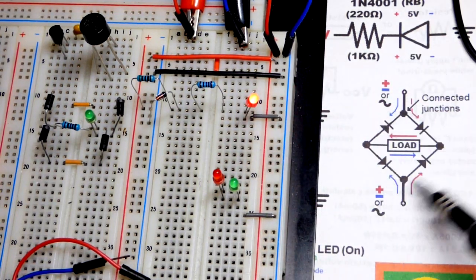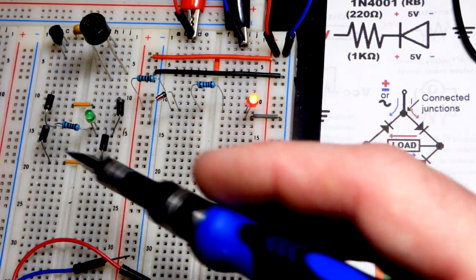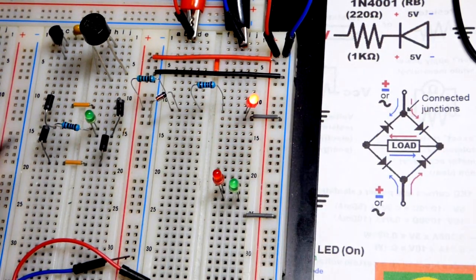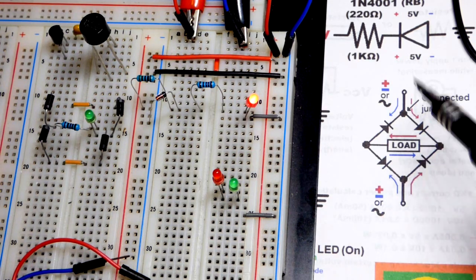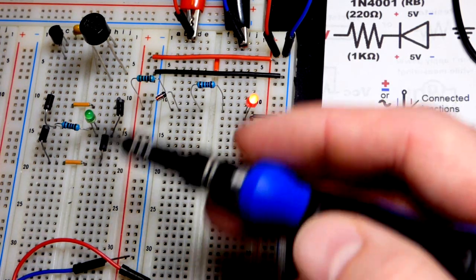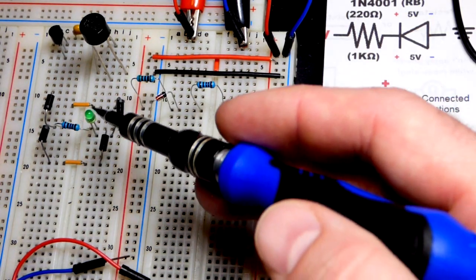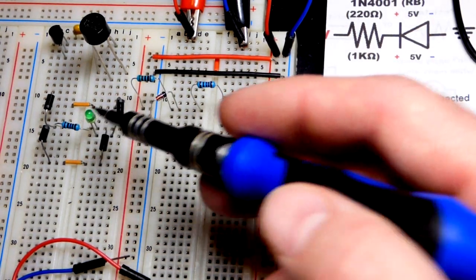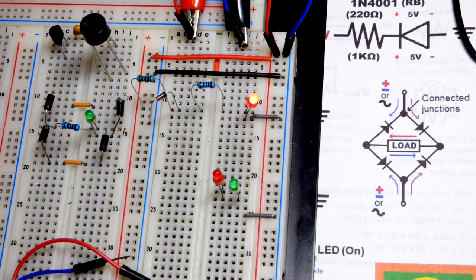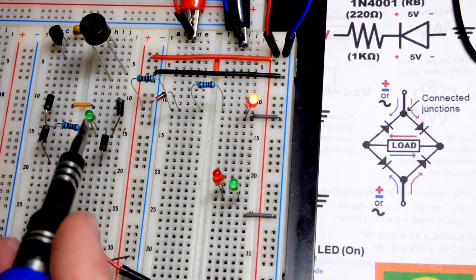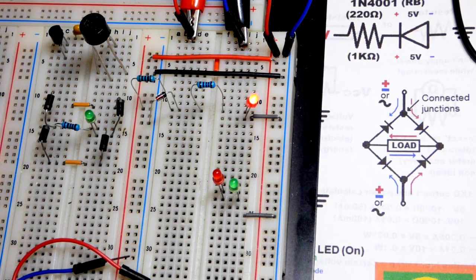But to begin with, we're going to look at 4 rectifier diodes here, and this is a full wave bridge rectifier. What it does is you can change the polarity across the circuit when it comes to power. Of course, loads like LEDs need the power in one direction. There's light bulbs and stuff that can work with current going both ways, but we don't really use light bulbs anymore. But the LED needs current going in the same direction.